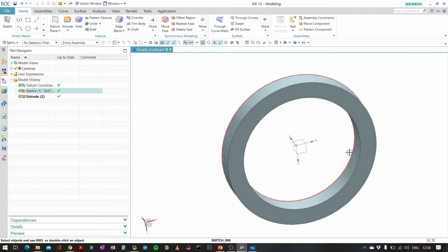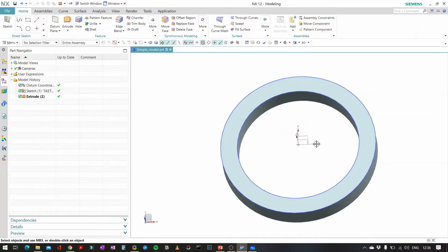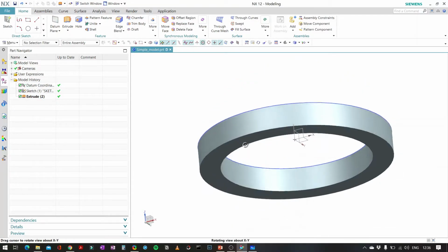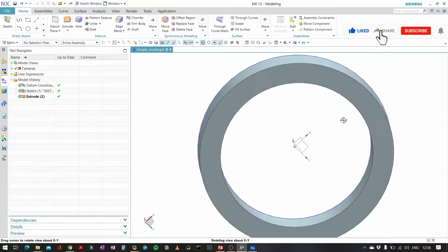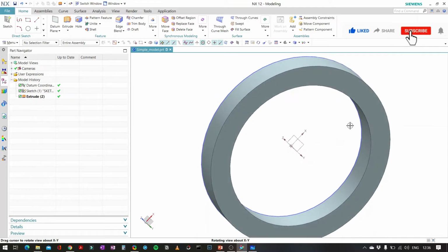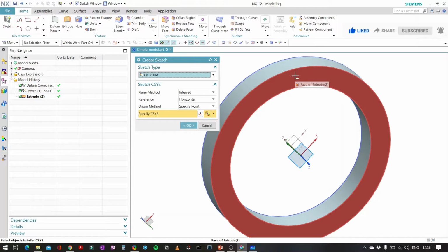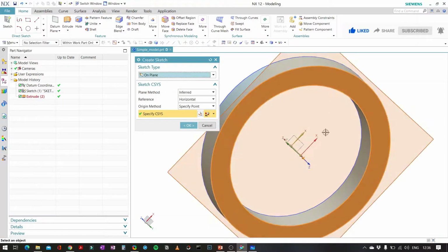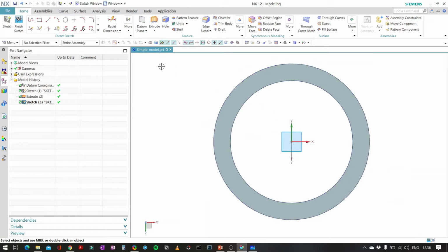So what we'll do similarly, now we had the plane over here automatically defined by the coordinate system, that is the XY plane. Now instead of selecting a plane, we'll select the already existing surface, the face of that extrusion. So it will create a dummy plane over there. We'll click OK. There are again two options.